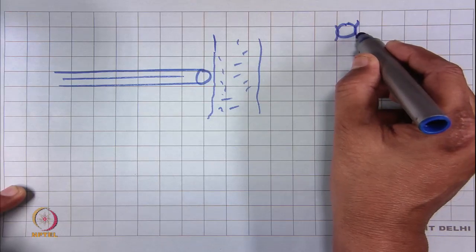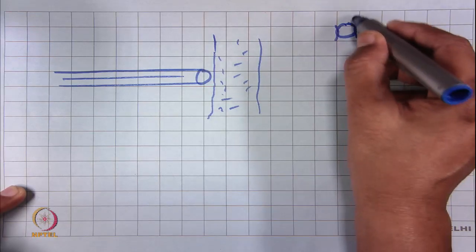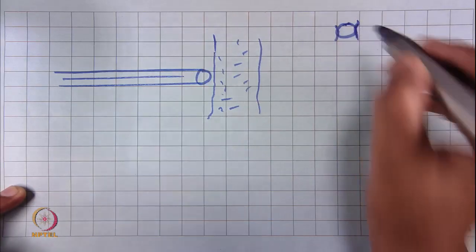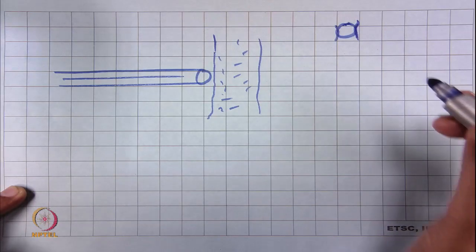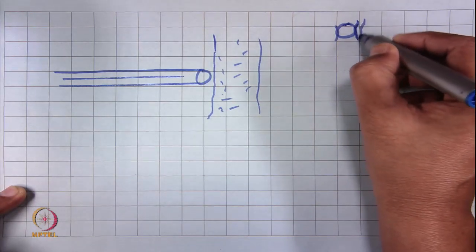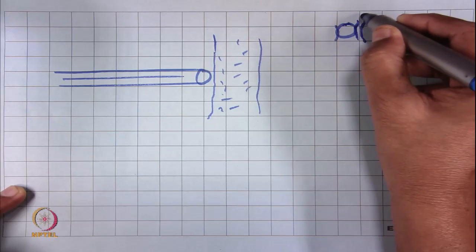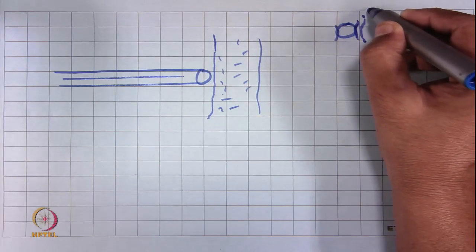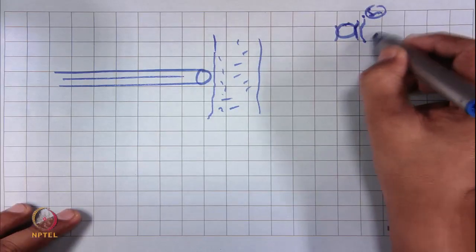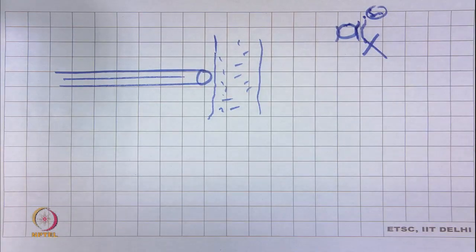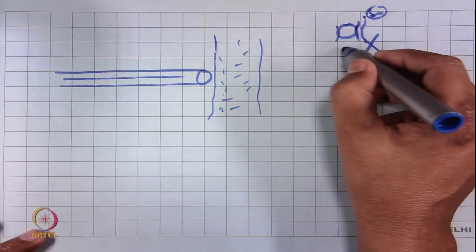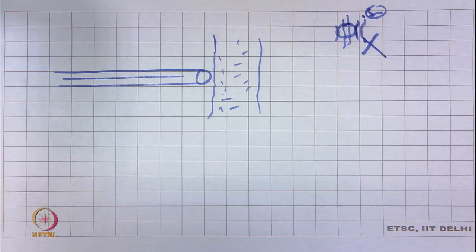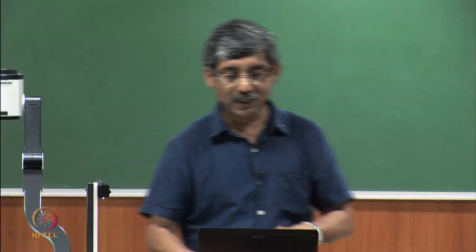If the partially projected fiber scatters, it will scatter a smaller quantity of light. So, that means this fiber will give a wrong result. It will show as if the fiber is smaller in diameter. So, that fiber we have to discard, and only fibers which cross completely, those fibers we have to take. Now, there is a technique that I will explain.